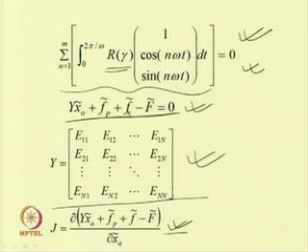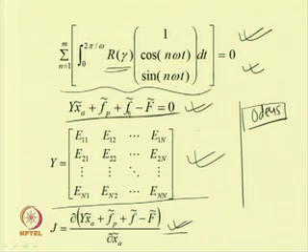If one uses MATLAB, then one can solve this differential equation by using ODE45, which is the 4th and 5th order Runge-Kutta method, but solving this large degrees of freedom system will require huge memory, space and computational time also. So, instead of doing that, one can solve this reduced equation, which is a set of algebraic equations, and one can get the solution very fast.